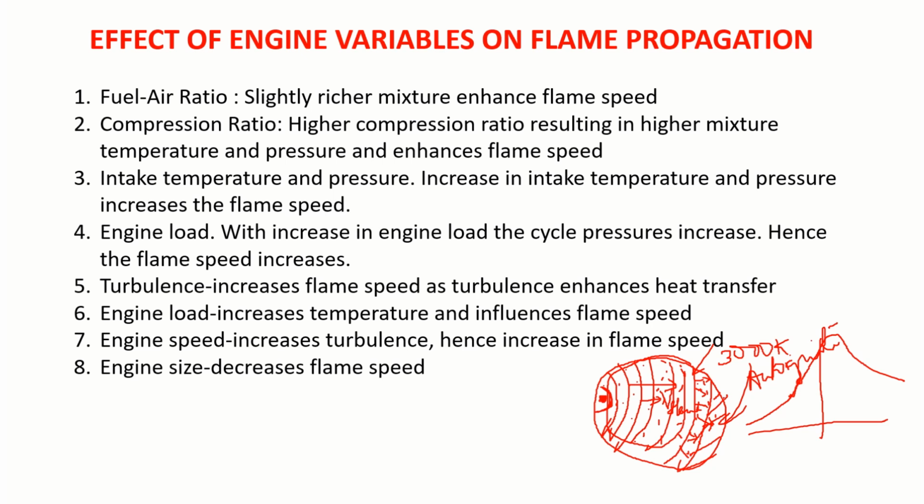So we should not give a chance for the end charge to auto-ignite. That means the flame should travel very fast and consume the charge before it prepares itself for auto-ignition. That's where flame propagation is important. Definitely that will help in even sizing of the engine cylinder, or how to increase this flame speed is very important.